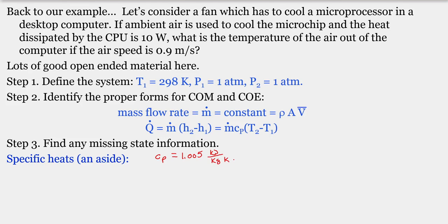Now, moving from this part of the equation to this part of the equation, remember we invoked the ideal gas assumption, the ideal gas model. I'm going to show you some more information on how to check if an ideal gas approximation is correct. At atmospheric conditions for air, it is. No worries. Remember, we went through the exercise of what are the types of conditions where we'd start to worry about ideal gas approximations: high pressures, cold temperatures. So we're not too worried in this system. In another example or two, I'll show you how to check that rigorously.